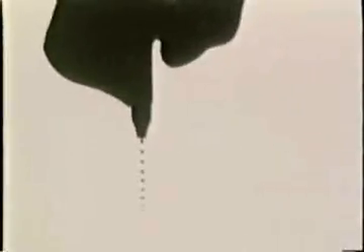This is an ordinary air hose from a machine shop. When we look at the jet with our Schlieren optical system, we find a typical pattern of expansion and compression waves. These waves are the mechanism of adjustment to the ambient pressure. The same pattern can be seen in a rocket exhaust when the outside pressure is not equal to the exit pressure. At very high altitudes, a poor match in pressure is unavoidable, and the expansion wave at a nozzle exit may turn the flow through a spectacular angle.